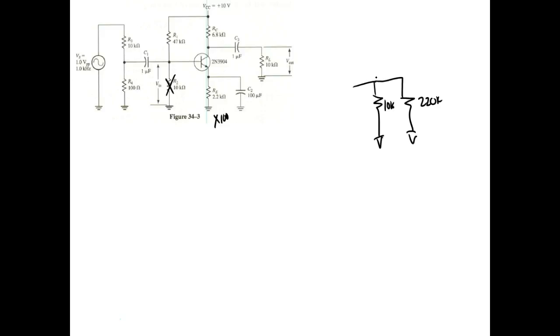You understand? Now this resistor right here is setting that voltage right there. So what we have now is basically a 47K and a 220K. So my base voltage is going to go way up. If my base voltage goes up, the transistor moves towards saturation, so the transistor is going to saturate. This is K up here, Rich.